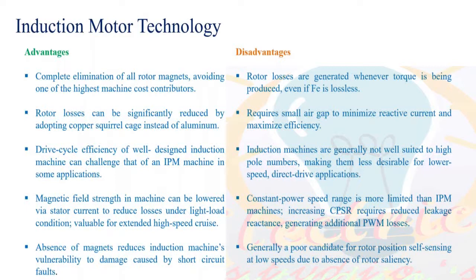That is why you can see the Tesla motors used in the Model S, the latest Model 3 and Model S, all these motors have the capability to run up to 18,000 RPM. They don't worry about the speed. But if it is a PMSM motor, yes, definitely I have to worry a lot, because that has an impact on the permanent magnet. So these are all the reasons that the induction motor is a very strong contender compared to PMSM.